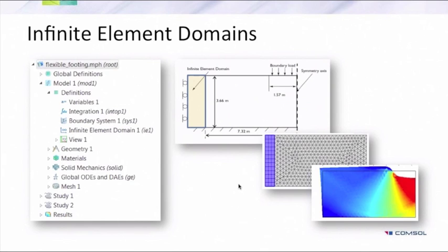When dealing with soil, many times you are faced with models which can be really big, while your deformation occurs locally. For example, if you have a slice of ground and you want to see what happens when you compress it in one point, the question is how far should you model in order to avoid the boundary effect. Since you don't want to model very large structures, this increases the computational time.